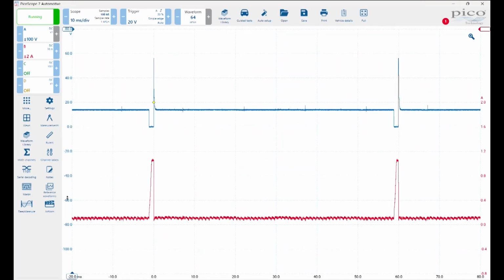And this often will show different things. In this case, we've got amps, but it could be pressure as well, and it just changes the scale. But we tend to call that the voltage scale, rightly or wrongly, and milliseconds, our time base along the bottom, which in this case is in milliseconds.